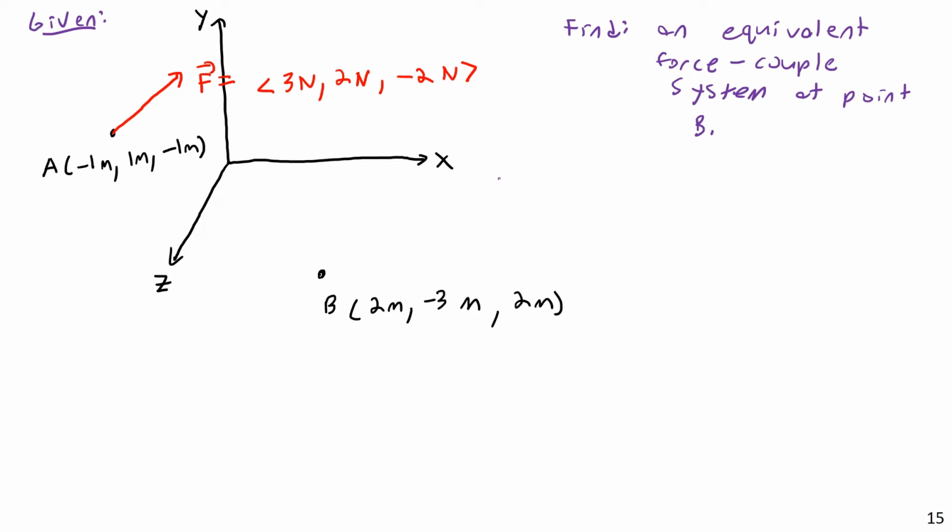I'm not going to do that for the sake of brevity, but I could do this equivalent force couple system, moving everything to B, then add up all the forces and all the moment vectors, and replace a dozen individual forces with a single force and a single couple located at B. If I had a whole bunch of forces all acting on one body, that would be a very easy way of collapsing it down to something much simpler and easier to handle.